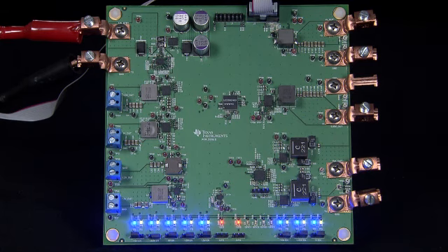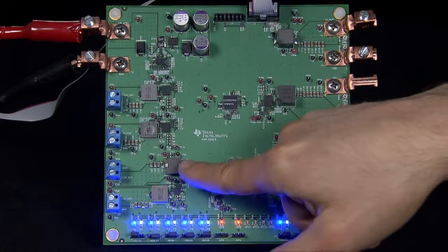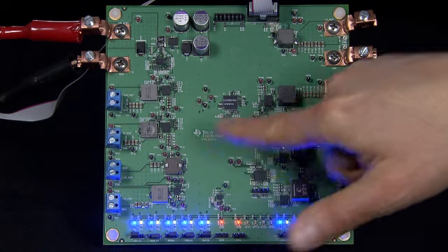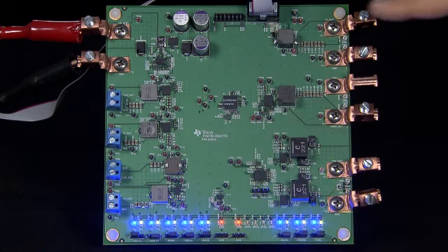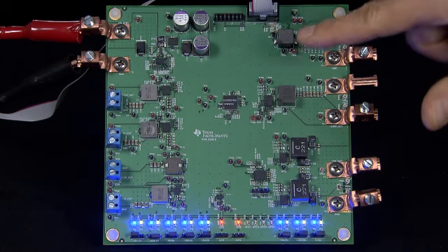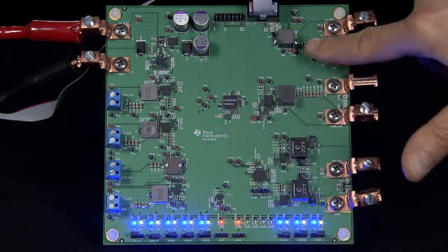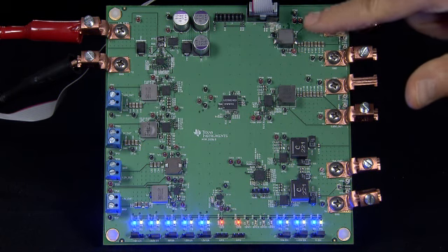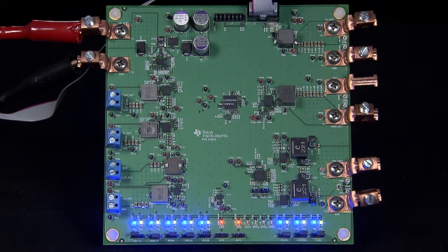Also in this design, you will see that we're employing inductor on top designs to minimize XY area on the PCB. These inductors have longer legs and stand on top of the ICs, allowing enough air gap to have excellent thermal performance while minimizing the X and Y area on the board as they stand on top of the IC and really reduce that PCB area. The complete PMP10896 TI design is fully downloadable from the TI Designs webpage with schematics, bill of materials, and layout files ready to be used.